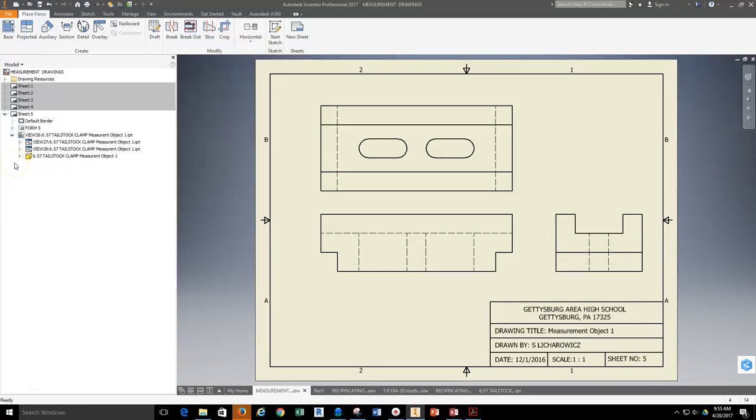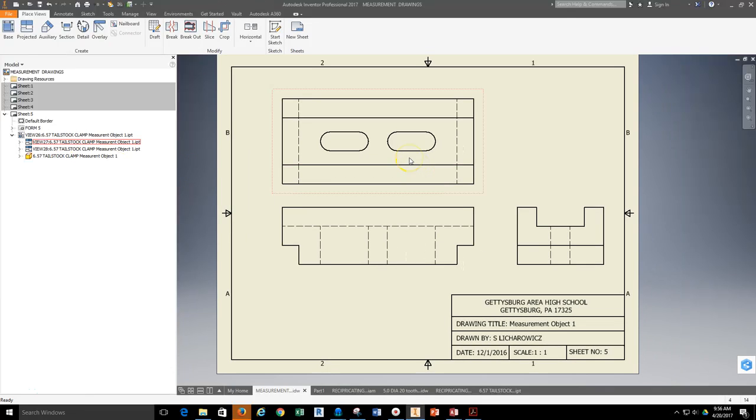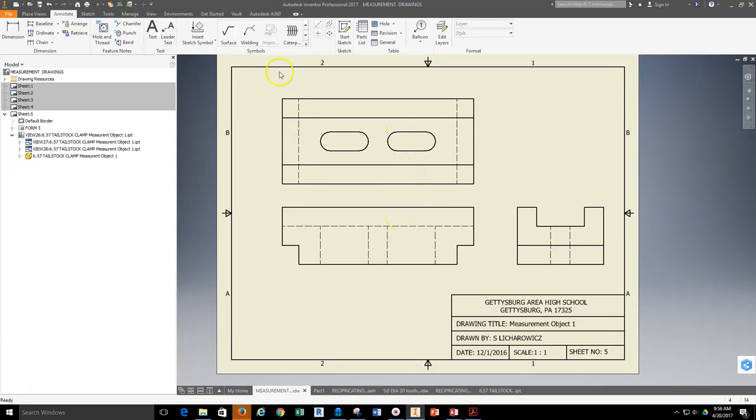Okay, in this video, we're going to walk through the basic steps to center mark and center line a drawing that has a slotted feature. When we lay out, this is the part of the assignment, the measure, model, and dimension assignment. When we start laying this out, we lay out our standard multi-view, and then we go right ahead to the first step in dimensioning and grab the annotation tab, grab our center mark tool, and we're going to start center marking the arc feature on the end of the slot.